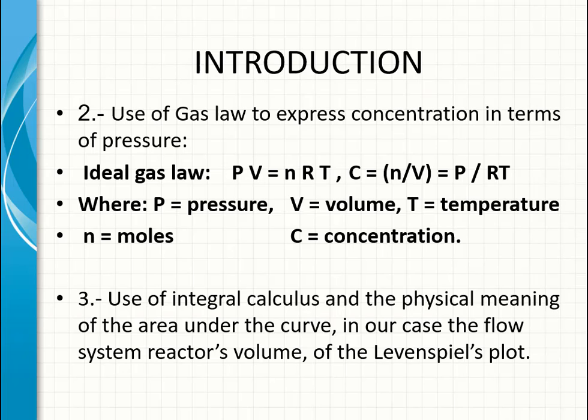Another concept that we are going to use is the integral calculus and the physical meaning of the area under the curve. In our case, the flow system's reactor volume on the 1/-rA plot. So the area under the curve of the 1/-rA plot is the volume of the reactor.